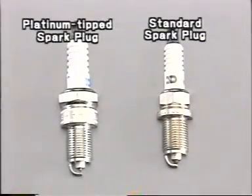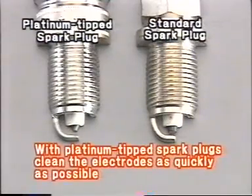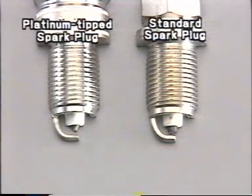In the case of a platinum tip spark plug, the tip of the center electrode and the opposing earth electrode are thinly plated with platinum. In principle, in order to protect the electrodes, they should not be cleaned. But if it becomes necessary to use a spark plug cleaner, for example because of soot, clean the electrodes as quickly as possible. It is not necessary to adjust the gap of a platinum spark plug.